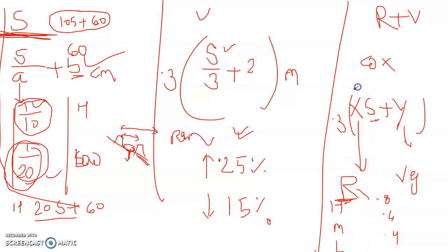So if it is a higher value, then vertical interval is increasing. If vertical interval is higher, then it is for low rainfall area. So I have written it in reverse order. Okay, so 0.8 will be for low, 0.6 will be for medium, and 0.4 will be for heavy rainfall. Because in heavy rainfall area you need a lower value of vertical interval, because you cannot make your two bunds at a very high distance. Okay, so this is how you have to apply the logic.